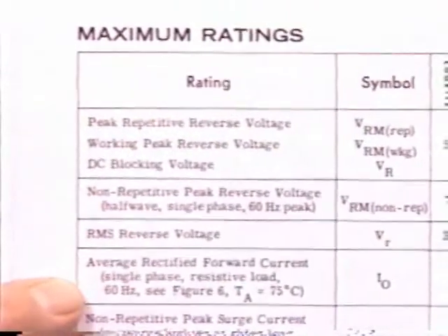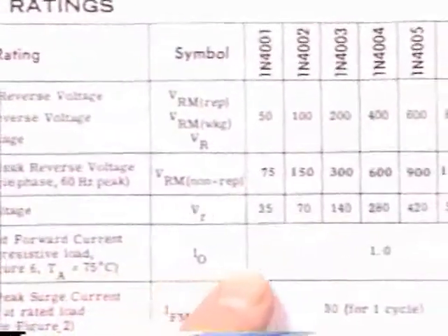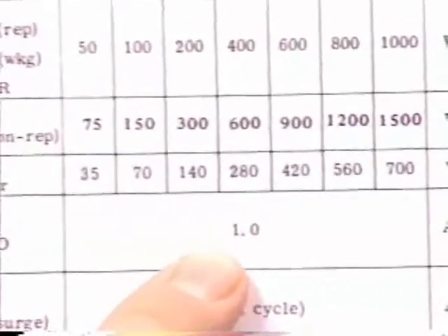Values for this specification often run in the range of 1 ampere of current. Since the diode can burn up if this limitation is exceeded, a current limiting resistor is usually placed in series with the diode. While there are some diode circuits, such as rectifiers, where this would not be necessary, it's important for the technician to know when and where current limiting resistors are required.